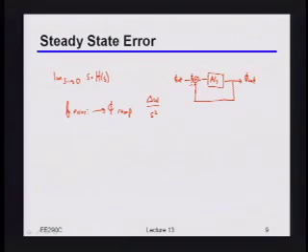So of course, my phi out over phi ref is just going to be something like a over s divided by 1 plus a over s. Which, if I simplify into a more standard form, would end up being 1 over s over a plus 1.